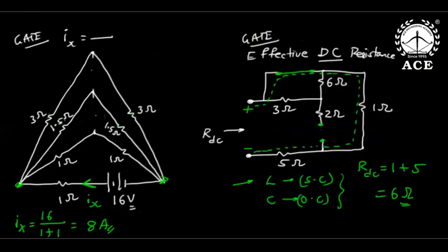Then this was another interesting one. Yesterday some students were arguing why this can't be a bridge. The reason is that there is some other connection at this junction, and even for this there is some connection at this junction. We cannot argue directly that it is a bridge. But the observation was that the mesh currents will be equal but opposite in direction. So the branch currents in the 2 ohm resistance and 4 ohm resistance will be 0. When current cannot flow through, those elements don't contribute resistance, so I remove them.